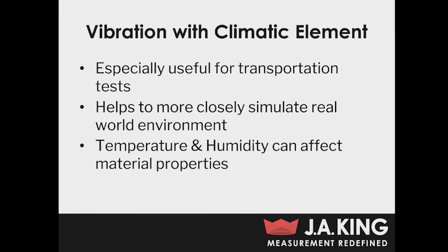Now, I also want to talk about the importance of including a climatic element in your vibration or your shock test. This can be especially useful for transportation tests. So if you think about having your part in the back of a truck, it's going to be bouncing around, it's going to experience vibration, it's going to experience possibly some shock, but it's also going to have some environmental conditions that are changing during this as well. So by including a climatic element in your test, it's going to help to more closely simulate that real world environment.